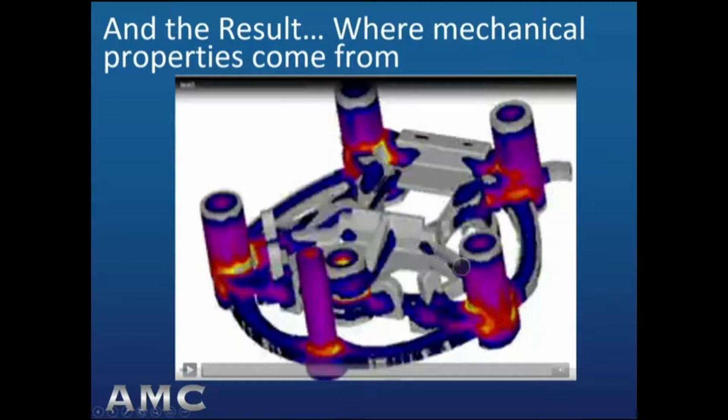So we're looking in the blue particularly at that time in which the feeding of the casting is at risk for getting too solid and not enough liquid in the mush. Those two blue spots that we see in the interior area, which is another high stress area of the casting, are in question. We want to make sure that those blue areas disappear as the casting continues to solidify, so that we have high integrity solidification for the mechanical properties that are going to be necessary in that high stress region in the center of the casting. So let's see how that plays out.